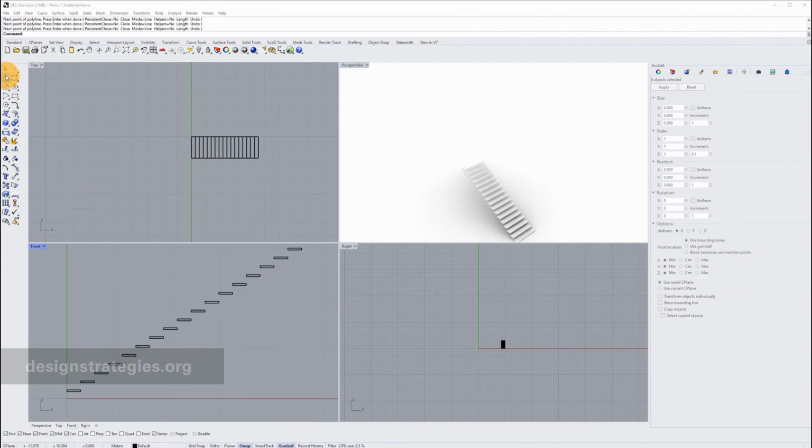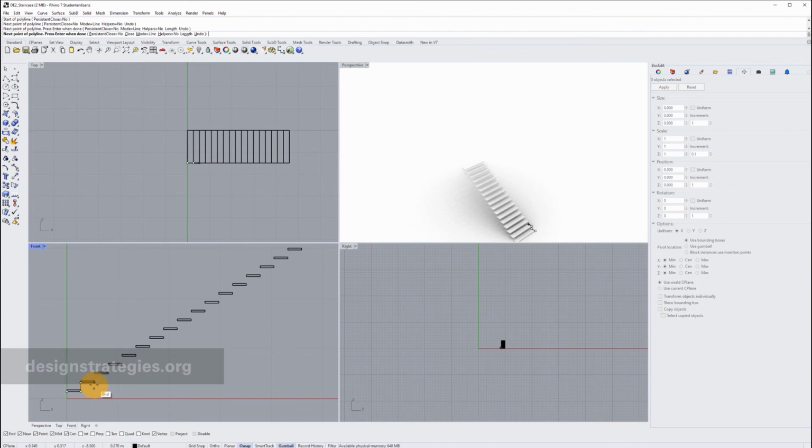I just take my poly tool and I just draw this substructure, and you can also see in my top view where it snaps, and it's really important that it snaps on one line. If you're a little bit insecure about this, you can also do everything in project, but it doesn't make sense now to change to project because I already started this. I just observe my top view so that it doesn't accidentally snap to the wrong point. Okay, somehow like this.